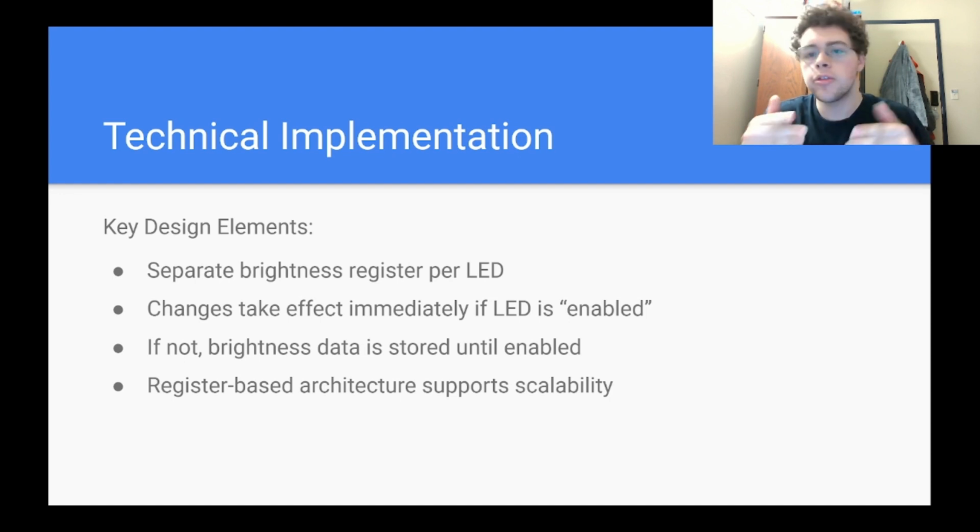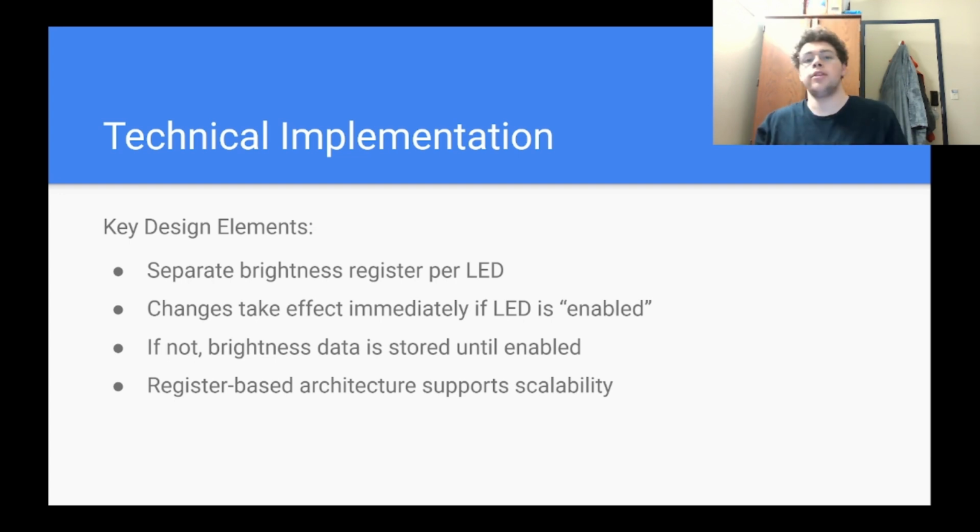Some key design elements to take note of about our API is that it separates the brightness register per LED, and change takes effect immediately if the LED is enabled. If the LED is not enabled or toggled, then that change will only happen once the LED is toggled again. And then also, due to the register-based architecture, this design will also support scalability.